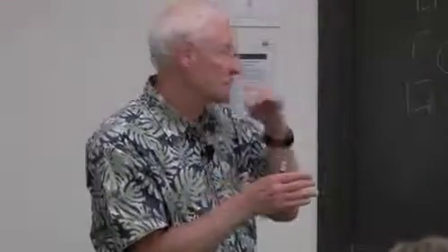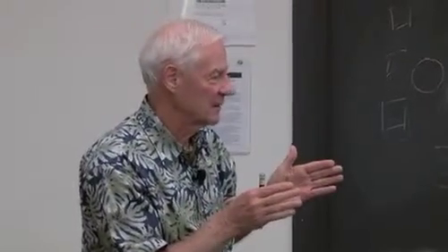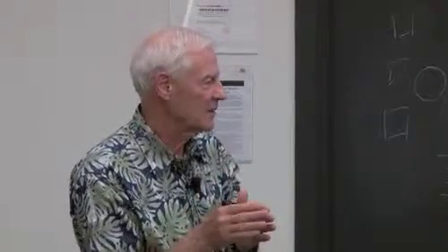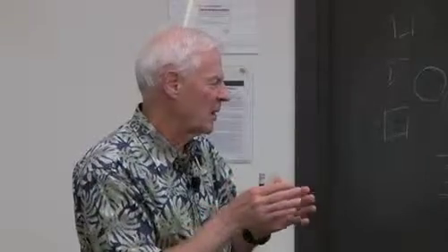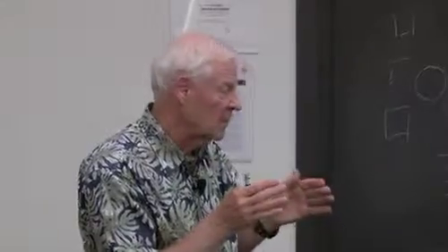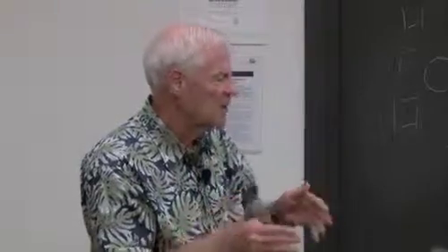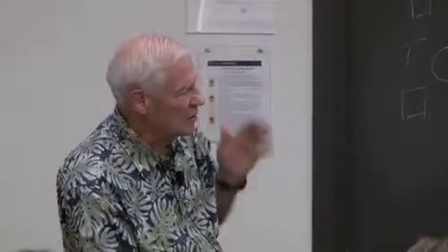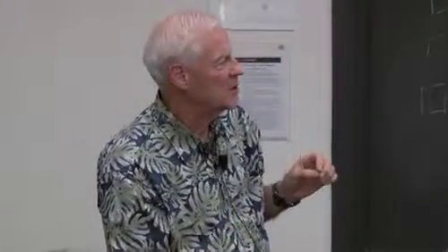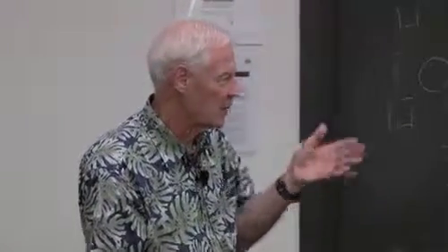Well, all of these tracers that I'm telling you about now, today, or in the last hour, are big molecules. So it suppresses the details of the spectroscopy, but it brings in what I call photophysics. So if it's isothermal, isobaric, life is easy. If it's a compressible flow, now I've got to be a little careful, but I need knowledge of the photophysics, and I need some kind of a model. We work on that. The small molecules means you have to understand the spectroscopy, pay attention to line shapes. But if you're trying to measure species which are formed in the flow, like NO or OH or formaldehyde or CH, that's what you have to do.